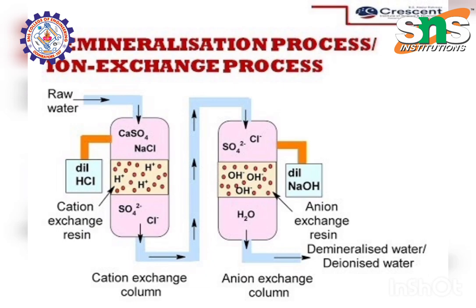If iron or manganese is present in the hard water, the turbidity increases in the ion exchange process, so that it cannot be filtered. And the equipment used in the ion exchange process is very costly. Also, more expensive chemicals are needed to remove the cations and anions. So these are the disadvantages in the ion exchange process.